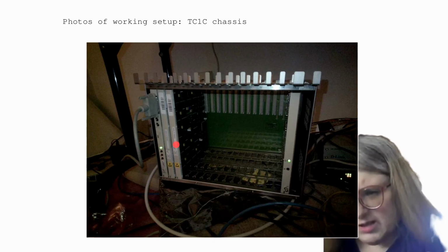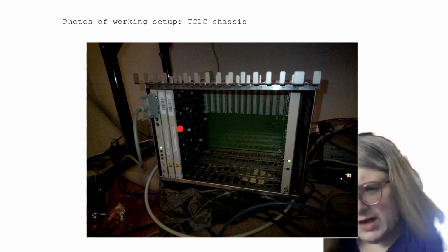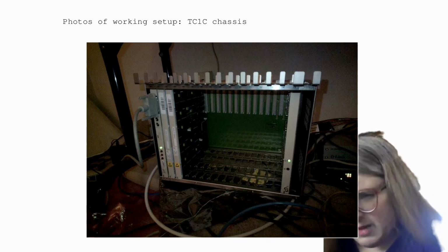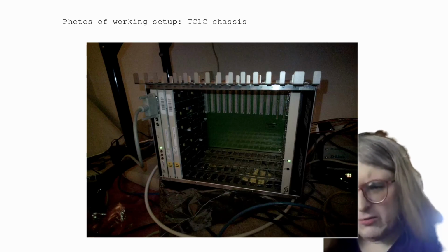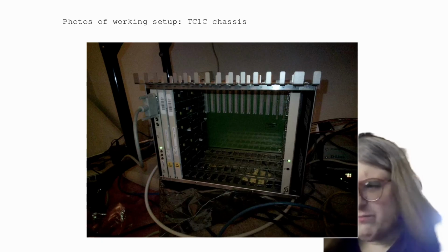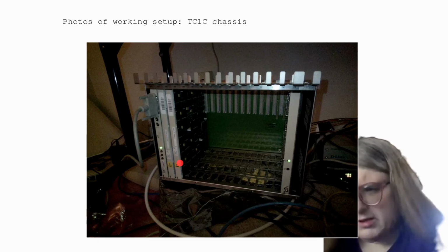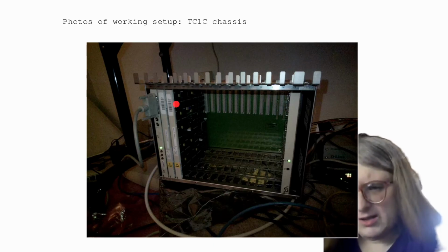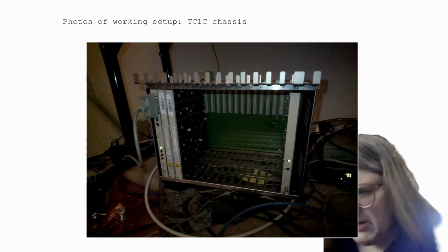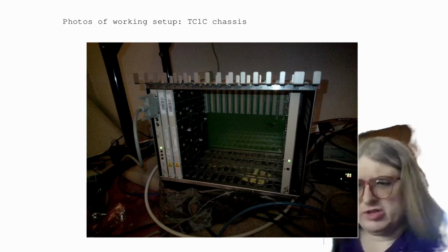Okay, so the transcoder cards, these are TR16s. Each of them is 1/2 of an E1, 16 channels. They also have a TR12 for T1 applications. The TR12, I've never had it in my hand. I don't know if they just took the TR16 and simply omitted 4 of the DSP chips, because we looked at this card in my first presentation, and they literally have a separate DSP chip for each transcoder channel. So on this TR16 card, there are 16 replicated DSP transcoder chips. So I wonder if on the TR12 they just omitted 4 of them. I'm not sure, just a guess.